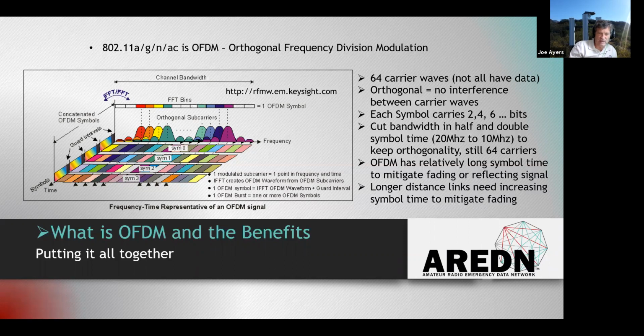But as we go to 10 megahertz, that's going to double, plus or minus, and 5 megahertz even farther than that. That's one of the reasons why, when we go to longer distances, 10 megahertz is a more optimal channel than 20 megahertz, because we'll start pushing into where the symbols start trashing the successive symbol at 20 megahertz. There's just not enough guard gap space there for it.